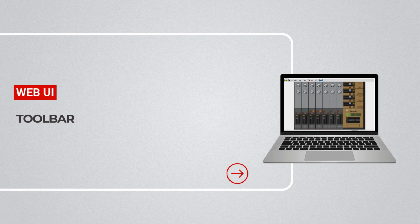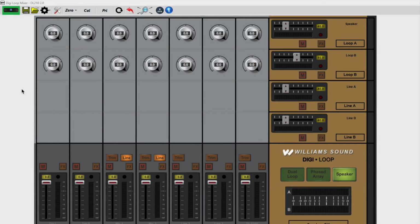Now let's do a quick overview of the top toolbar on the PC app. The amplifier connection icon. This icon is on the very top left of the app. Once your settings are established, click this button to connect the amplifier to the PC. A green background means that it connected successfully. A red background means the connection failed. Then check your connections and your protocol and try again.